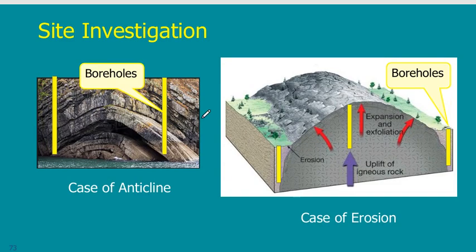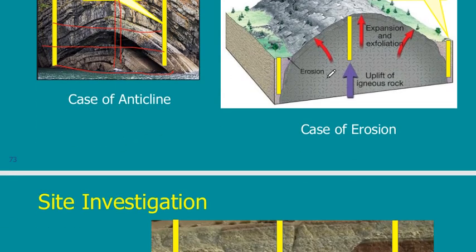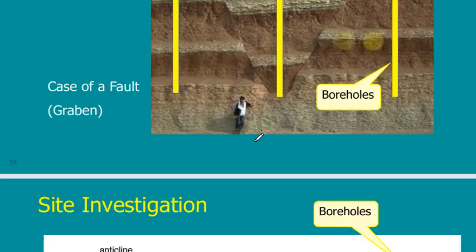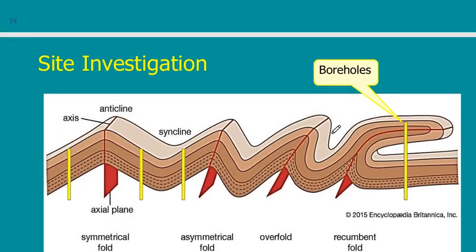So this is what I can do with the site investigation. Take a borehole here and there. Of course, it would give me a wrong impression that I have horizontal layers. I don't have horizontal layers. I have curved layers. So if I take a borehole in between, it would be good. And so on in all of the geologic features that I have studied.